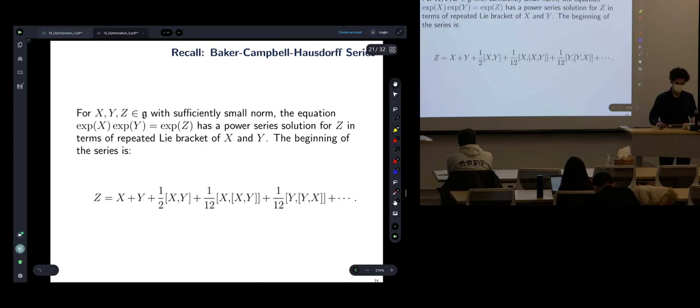So let's see how, in general, we can linearize a residual that is on a Lie group, and that will allow us to solve a pose graph problem. That's the SLAM problem, where there are a bunch of poses connected on a graph, and the measurements, the constraints, are relative rigid body transformations. It's called pose synchronization, or we call it pose graph.